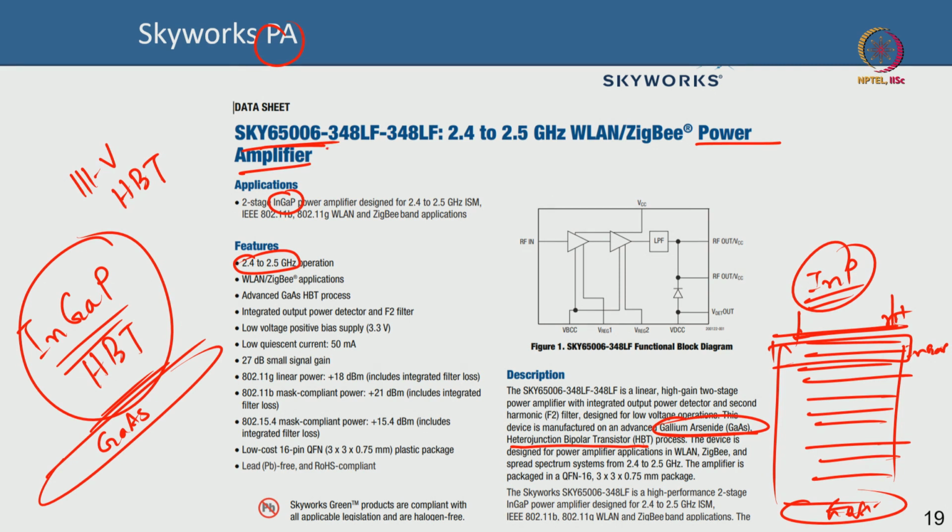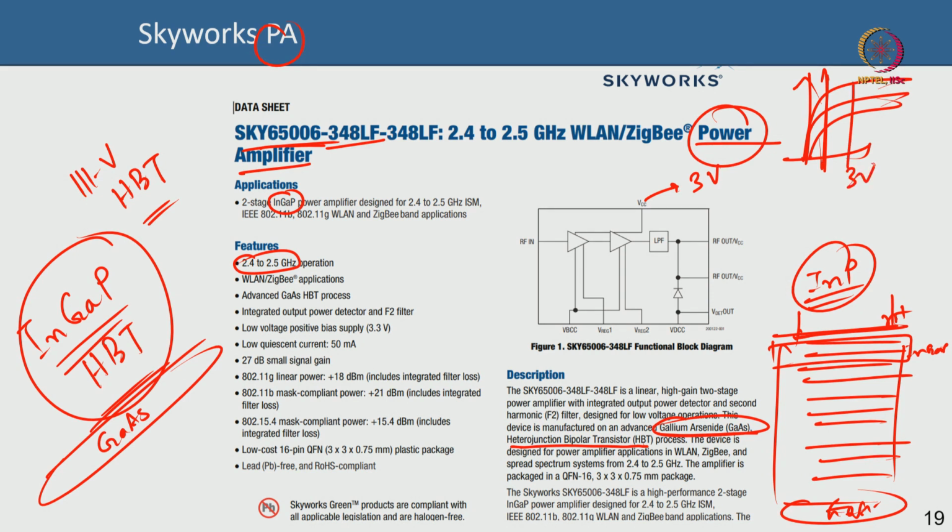You see, Skyworks is supplying that front end module. The front end module has the power amplifier in the transmitting chain, correct? In a cell phone your supply voltage will be probably around 3 volt, 3.3 volt, which means you need to get power out in this power amplifier at 3 volt max, which means if you have ID characteristics, your knee voltage must be much lower than 3 volt, because at 3 volt you need to get power out.